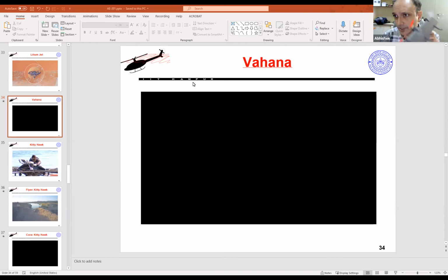So it will separate. Sometimes your angle of attack may not be that high, but something else can cause adverse pressure gradient, or it can disturb the flow, causing a separation. Such things are, for example, shock waves. If the flow over the airfoil becomes supersonic, the ambient flow or the free stream flow may still be subsonic, less than the speed of sound.